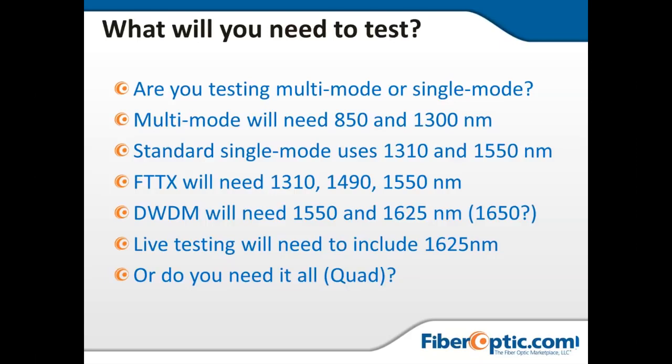So with the 850, we'll be able to get a pretty clear reference of what the fiber looks like at 850. But if we see a certain location on that OTDR trace where the 1300 nanometer wavelength has a higher drop off or a higher amount of loss at a particular event than at the 850, then we know we have a macro bend in that location, and that's something we'll probably want to clean up. So that's why we'll need 850 and 1300. Always recommending those two wavelengths.